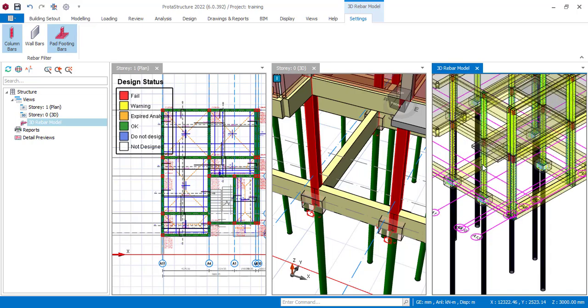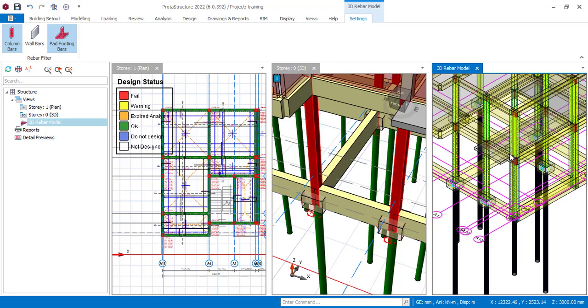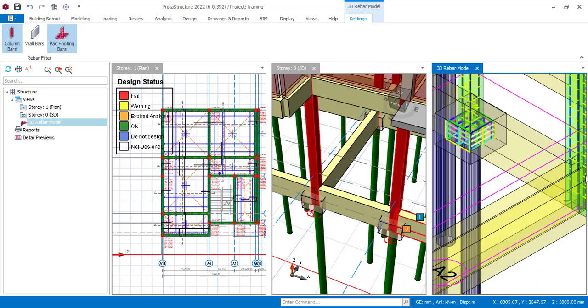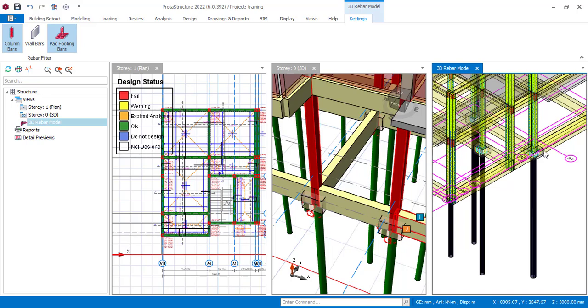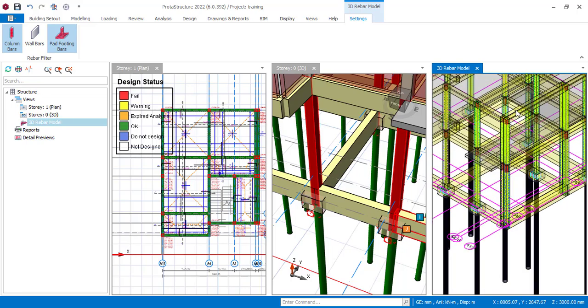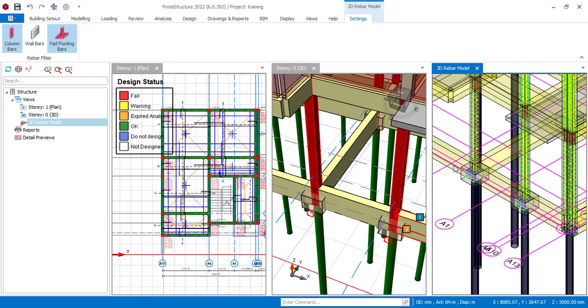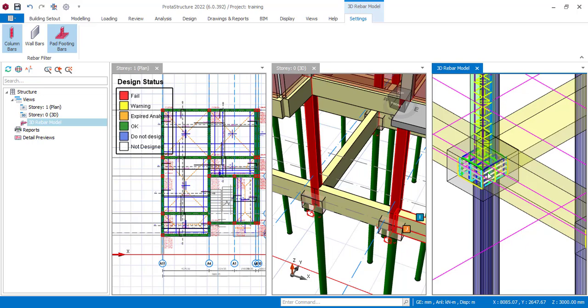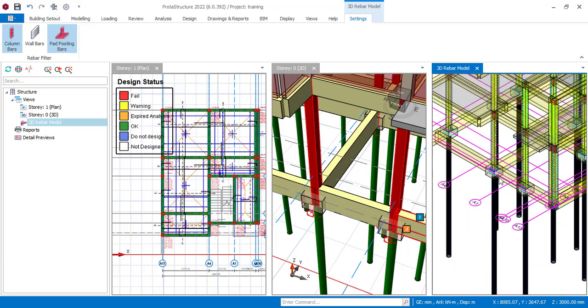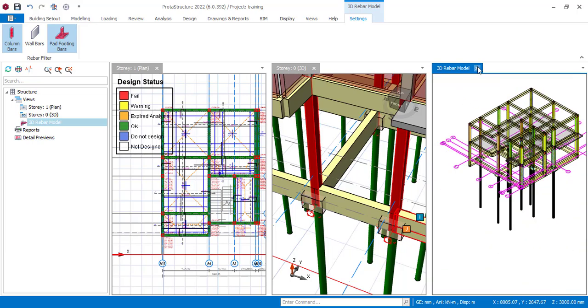From the design parameters there, I'm supposed to change the reinforcement to only bottom. Then for my combine, I'm supposed to leave it as top and bottom. Okay, however, I have displayed that when I was dealing with the pad footing, but you know, this is actually our pile cap. It's not a pad, it's the pile cap, which is what I have here. Okay, so that is that. I can just close it if I'm satisfied with what I'm seeing.